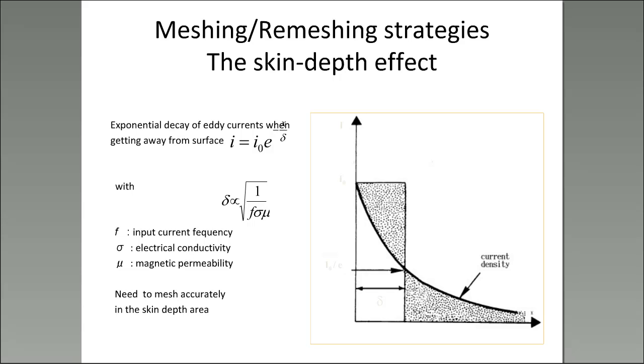That's why, in fact, I said previously that it seems to me that the global finite element approach for space discretization is much more adapted for parallel computing than the approach using boundary elements. Because there, for instance, you can use mesh partitioning algorithms which try to get roughly the same number of elements on each submesh. And also, you try to minimize the interface size between the submeshes. Why? Because this minimizes the cost of interprocessor communications.